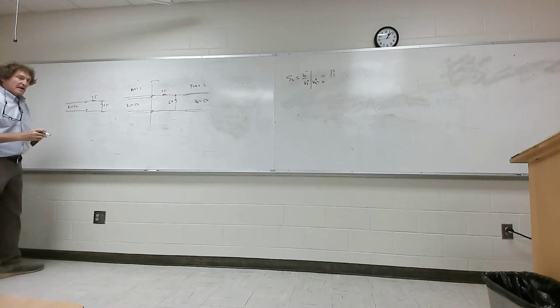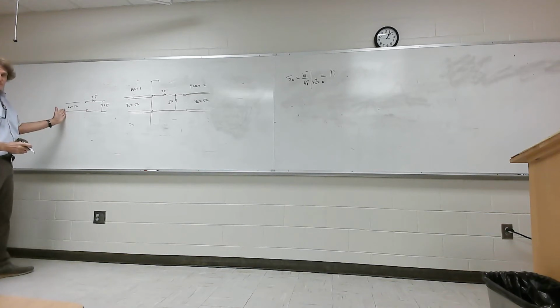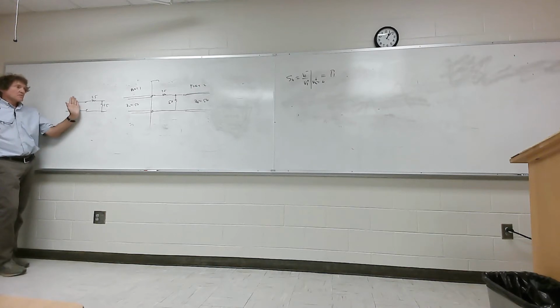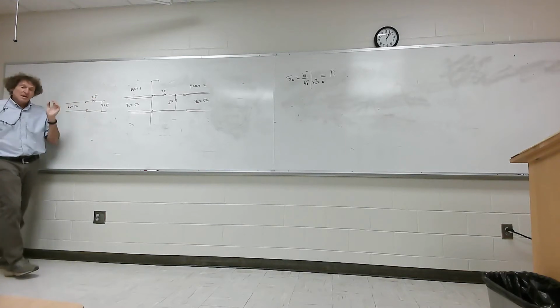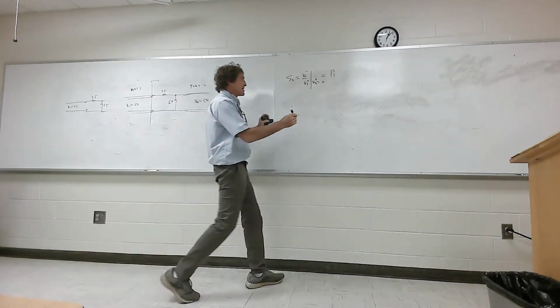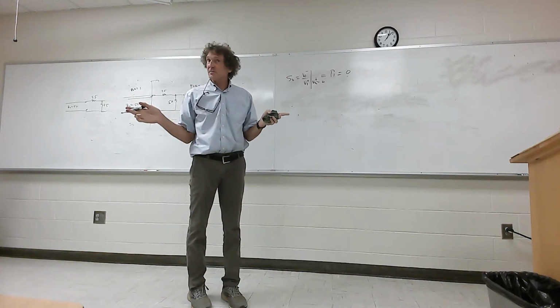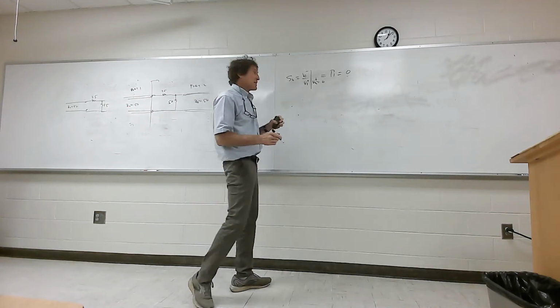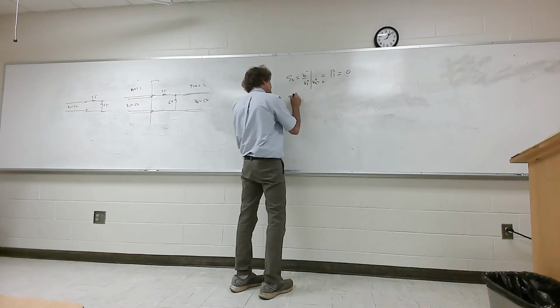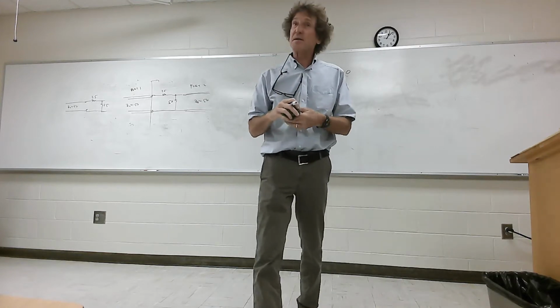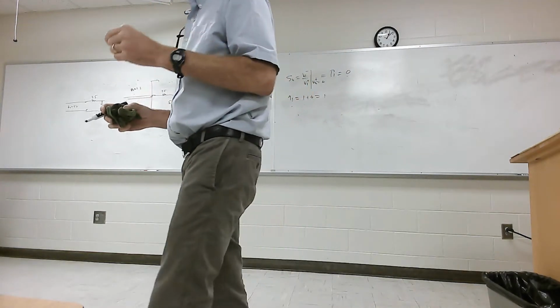And when you look at that, what's the reflection coefficient? Now just think about this. It's as obvious as it seems. What am I going into? What impedance? 50. Where did that come from? So 50 minus 50 is 0. That's nice. That's what we like to see. So it's 0. Y'all understand the reason? All right, now, if that's 0, what's the transmission coefficient? 1 plus 0 is 1. Makes sense. Nothing reflected, everything's transmitted. This should make sense to everybody.